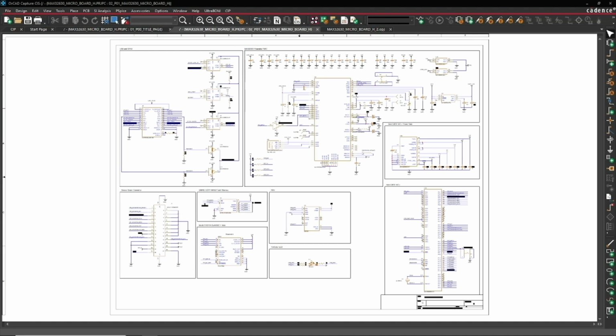Input, process, output. Then I block off entire sections of the design that support these major input, process, output functions. Only after I understand the functions and what roles they play in the inputs, processing, and outputs do I get into more details. I'll demonstrate this method in this design. Let's look at inputs. The primary input and function to any design is power. Why power first? Well, every printed circuit board needs power to make the PCB work. If power fails, then so does everything else. So I always start with power.